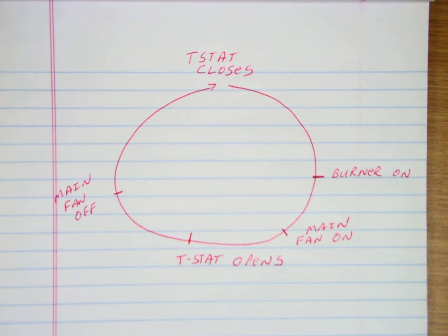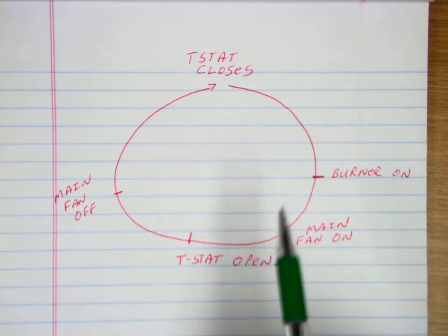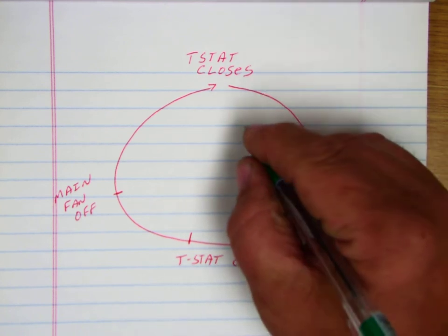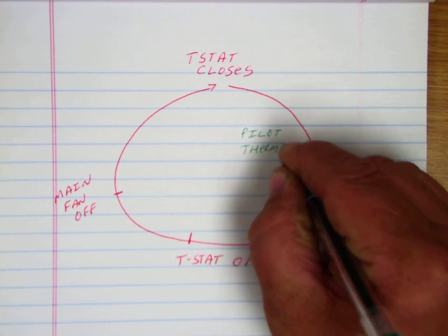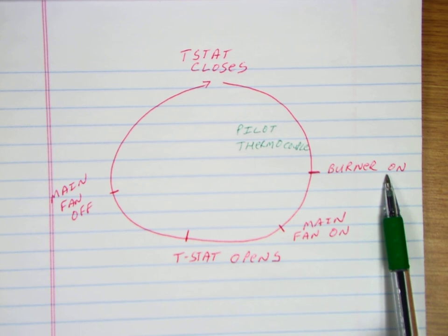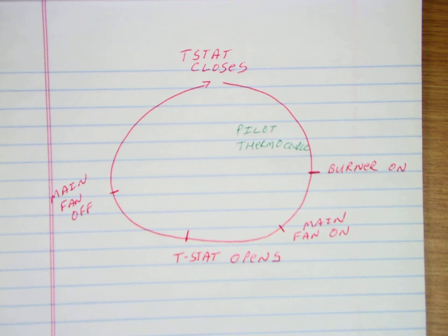So I'm going to refer to them both as an efficient furnace in this video. To start out with, in our basic furnace, the old school standing pilot light, once the T-stat closed, as long as there was a pilot light that was holding the thermocouple, which was enabling the gas valve, as soon as the thermostat closed, we powered the gas valve, which shot gas onto that pilot light, and the burner lit. Right? It was pretty simple.